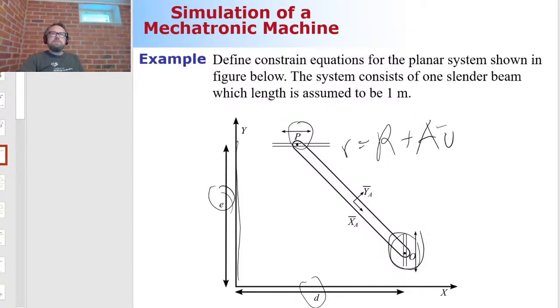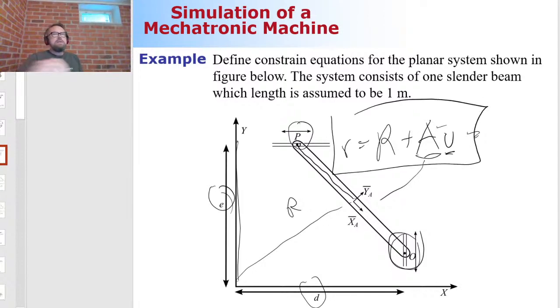This equation describes a point with respect to the global coordinate system. First we have here R, which describes where the body reference coordinate system is traveling. Then this guy here takes the rotation of the body reference coordinate system into account. And vector u bar allows us to travel wherever we want. Now we want to go to one end of this beam-like body. And once we have this equation, then we're going to introduce the constraint, which says that this point, by the way, is no longer free to move as it wants, but it's going to be subject to constraints. So that's the concept. It's all about this equation.